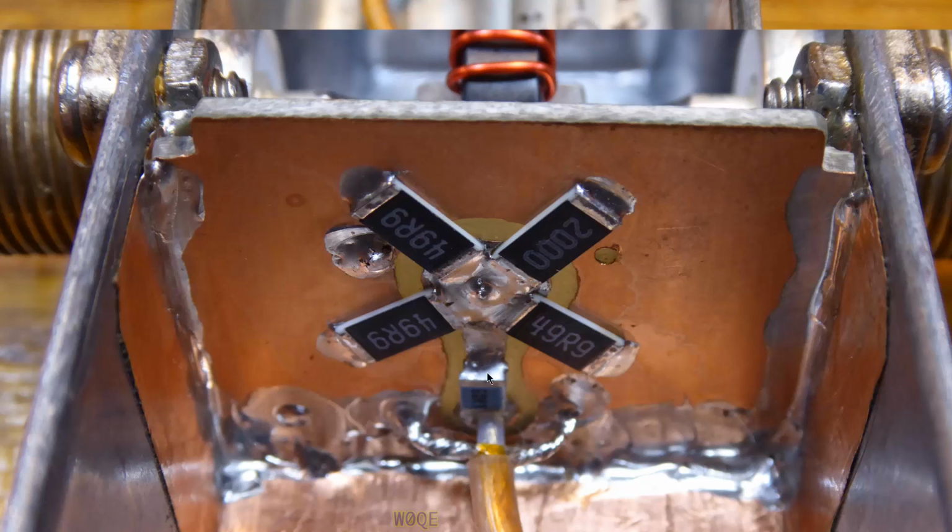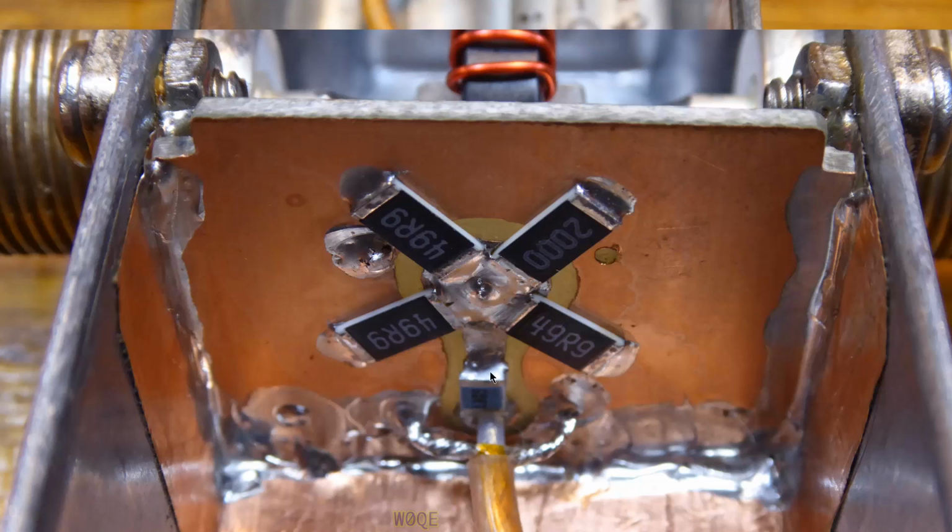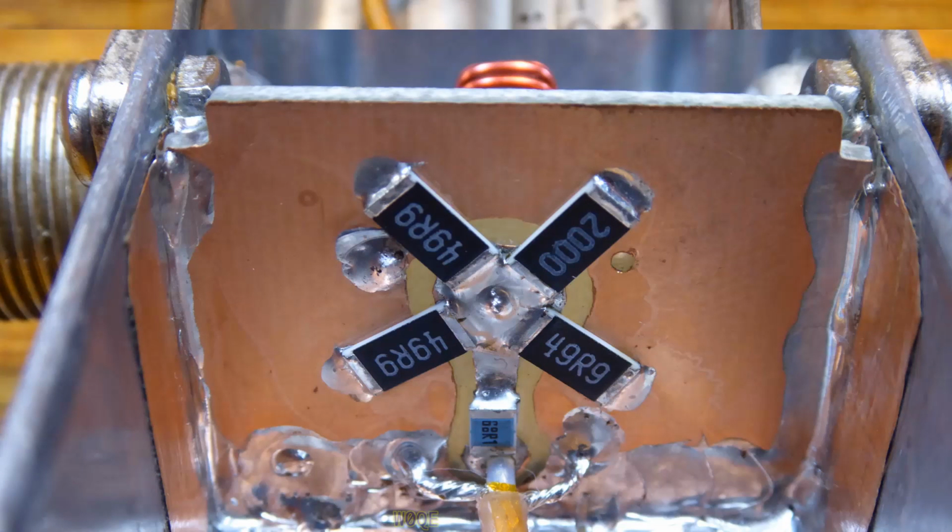Here's two stacked. These are 2512 resistors. They're good for 1 watt each. These are a couple 0805s, I believe, and they're 68 ohms, 68.1s, which give me 34 point something ohms. So this circuit represents pretty much what I've got in SimSmith in the ruse block. Here's another picture which shows this maybe a little bit easier because I had it backlit.